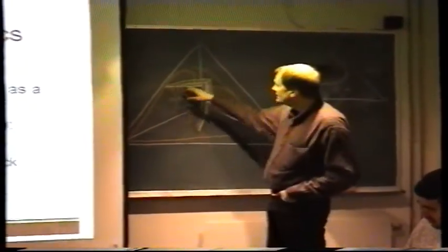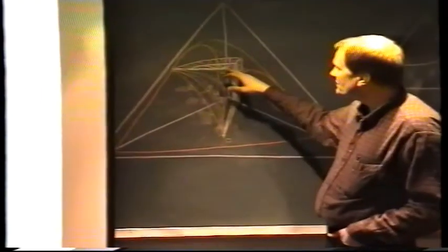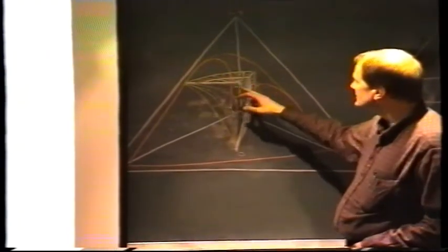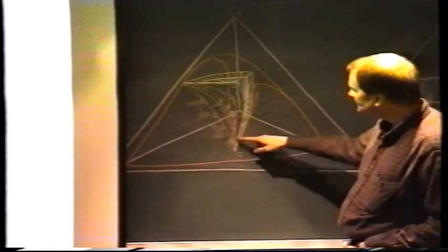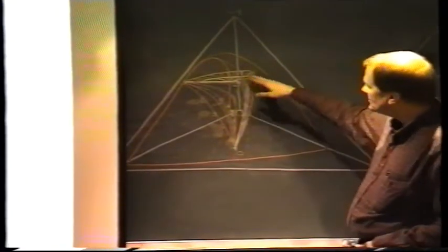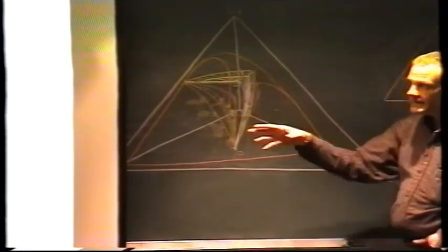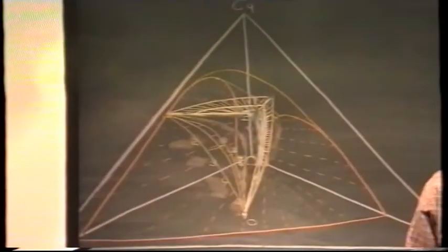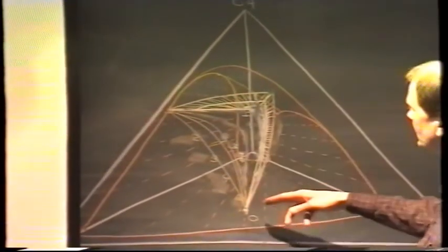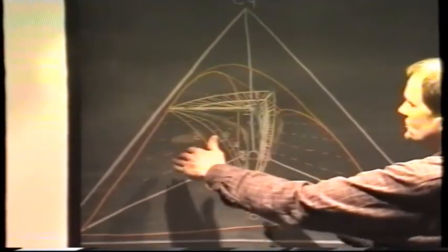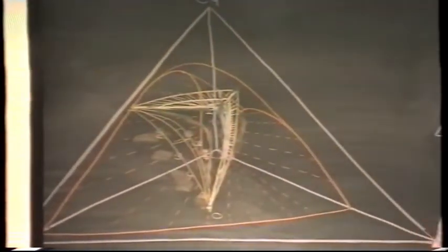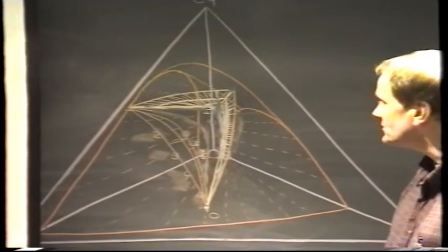There's the tie line that passes through the original injection gas. There's the tie line that passes through the original oil, and then there's this tie line that they call the crossover tie line, where the two compositional paths intersect. The two halves of the compositional path intersect.